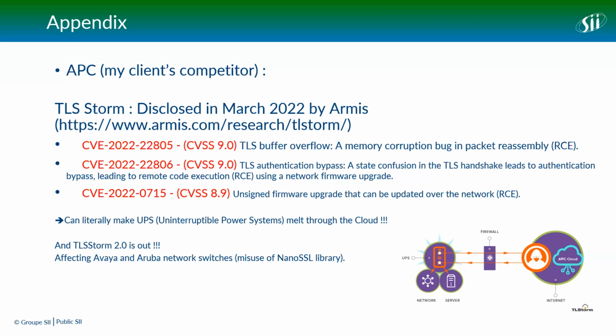So with all the things we saw before, especially for cybersecurity, with OP-TEE we guarantee the signature. We have the root of trust and the secure boot. We prevent malicious firmware from being uploaded and loaded by the devices. And crypto could also help for the second point, because for TLS and so on, we could have some protection on the certificates and private keys.